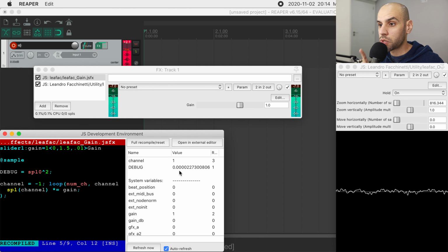Okay, working with these numbers would be inconvenient, wouldn't it? If you wanted to change the volume on this waveform, not by 6 dB, but by 0.000000213, that is inconvenient. So a solution for this is to take the log of this number. And we want to take the log in base 10. So we use this function. So now we are talking about numbers that are more reasonable, okay? These numbers make more sense.